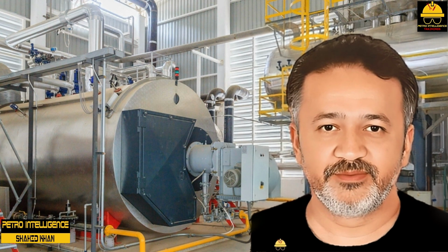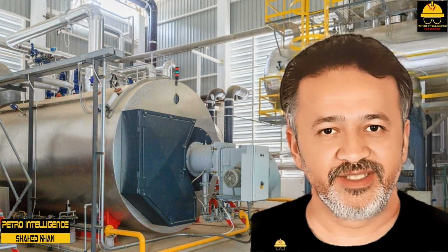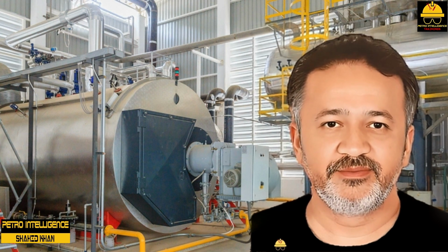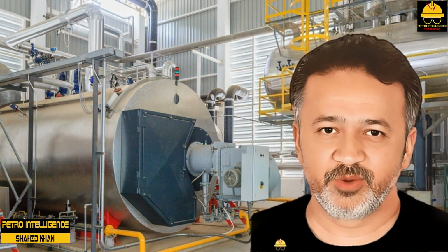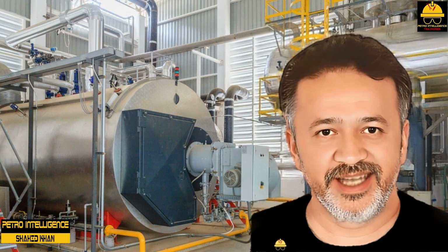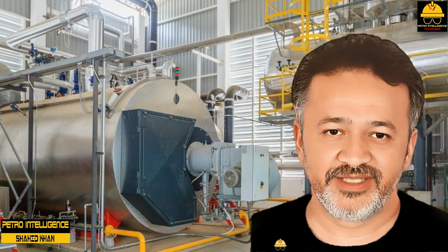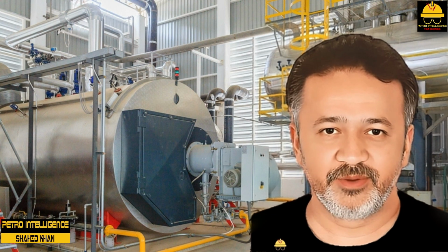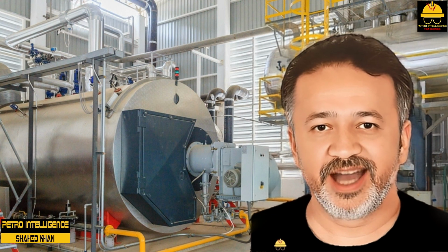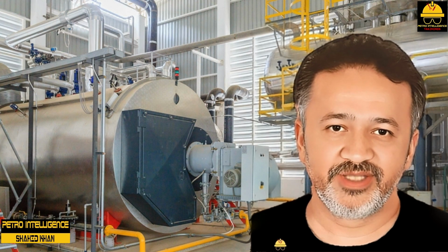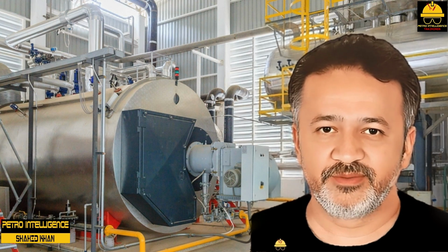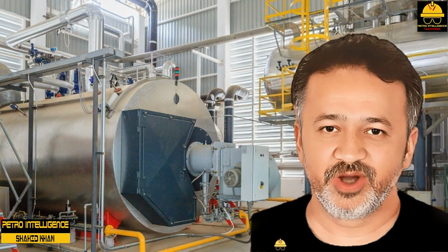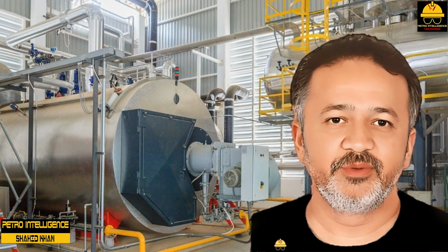Firetube boilers. A more complicated boiler is the firetube boiler, which resembles a modified shell and tube heat exchanger. This type of boiler is composed of a shell and a series of tubes designed to transfer heat from the fire tubes into boiler feed water. Combustion gases exit through a chamber similar to an exchanger head and pass safely out of the boiler. The water level in the boiler shell is maintained above the tubes to protect them from overheating. The term firetube denotes that the heat source is from within the tubes.